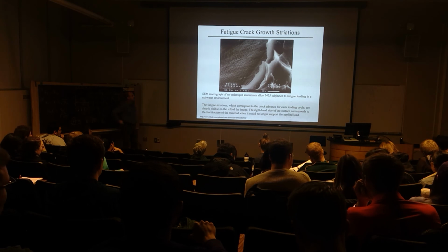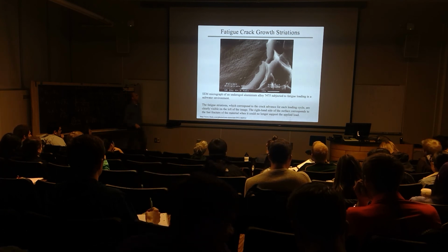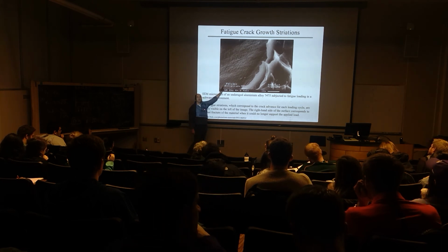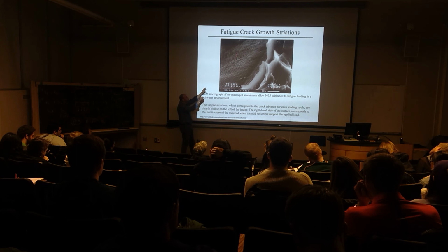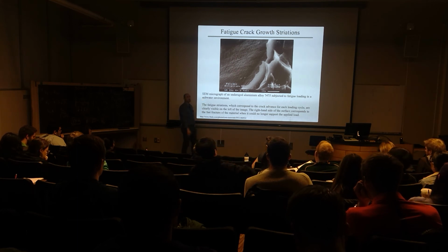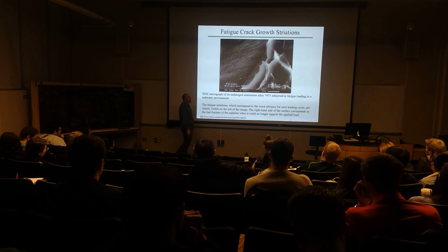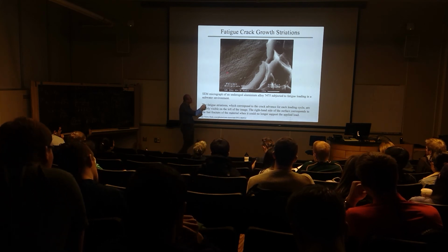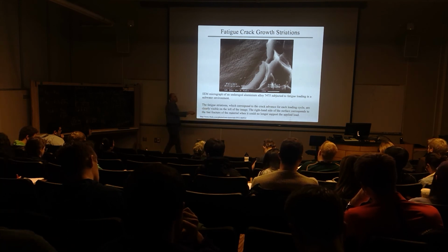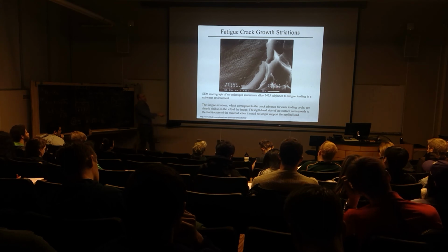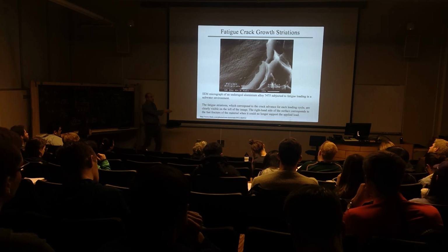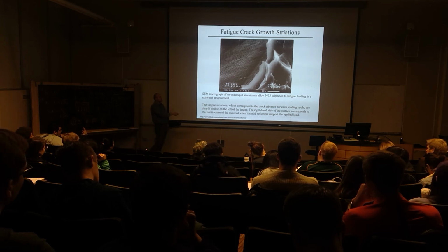But when we see fracture surfaces, what we look for is striations. And so this is the most common characteristic of fatigue crack growth. These striations are a result of the incremental extension of the crack with each loading cycle. And they are then a trace of the path that the crack followed until it gets to a point of instability or ultimate fracture. And then what we see is the onset. At this very high magnification, you're looking at a singular void because of ductility in this material that took place.